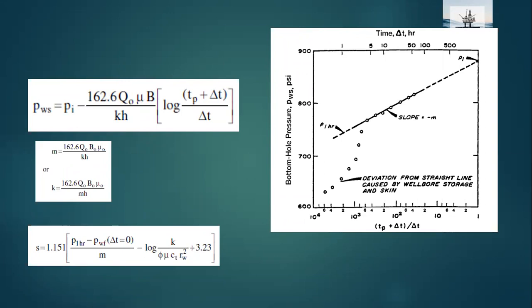There is a zone which has been damaged, so the fluid flowing towards the well is constricted by this barrier and has to bypass it. That could take around 1 hour. So the initial 1 hour is the time where the fluid is bypassing through this skin zone. Because of that, there is a deviation in the rise. It is not rising linearly, but in a curved, deviated way.